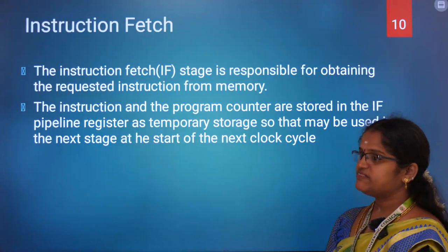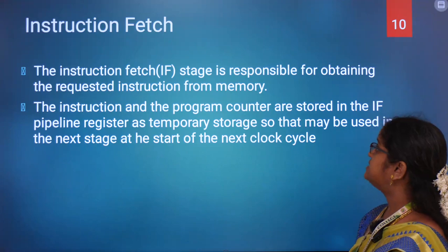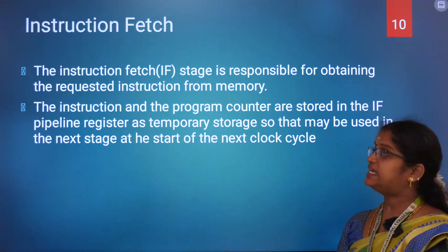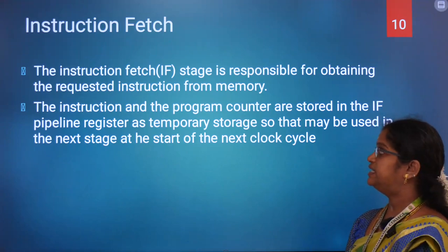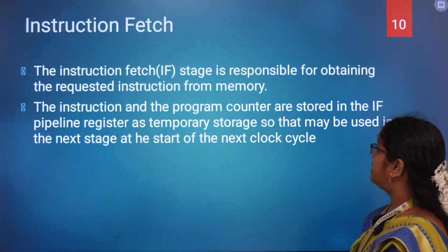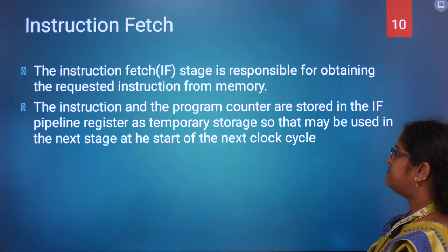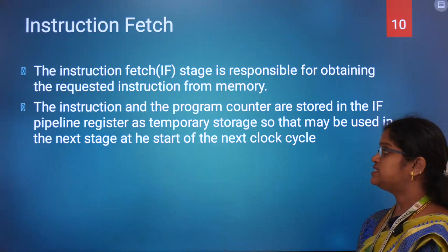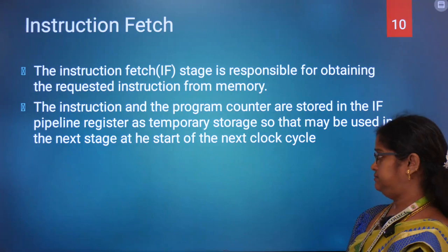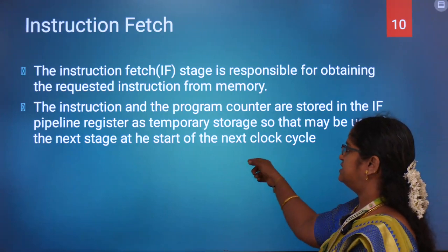Instruction fetch. Instruction fetch means it's a stage responsible for obtaining the requested instruction from memory. The instruction and the program counter are stored in the IF pipeline register as temporary storage, so that they may be used in the next stage at the start of the next clock cycle.